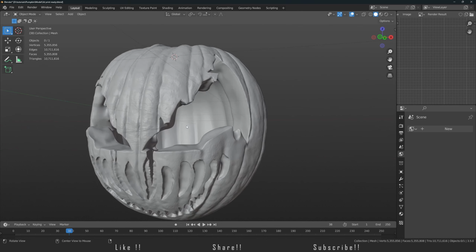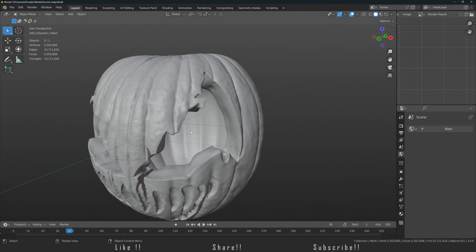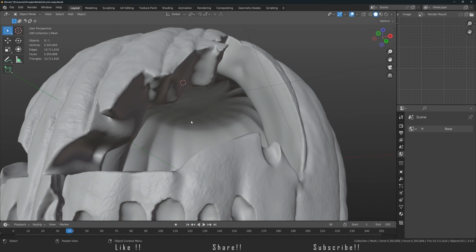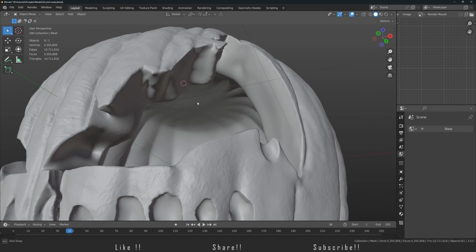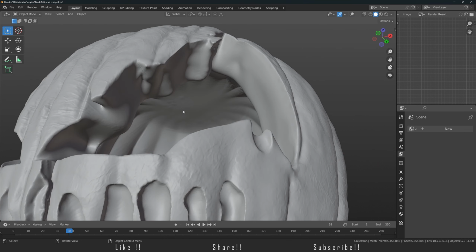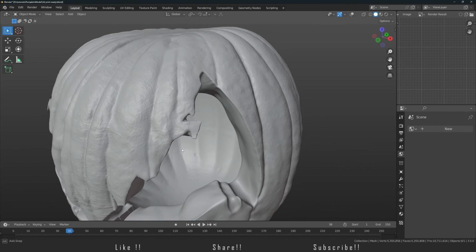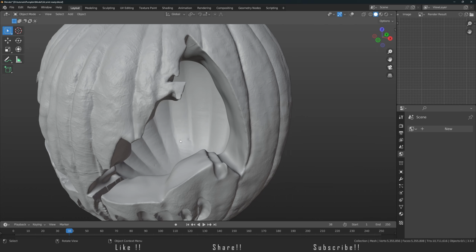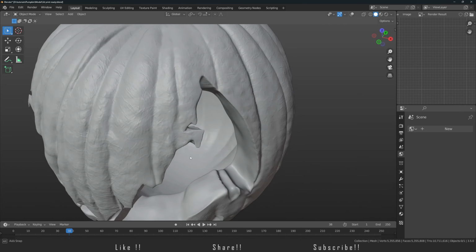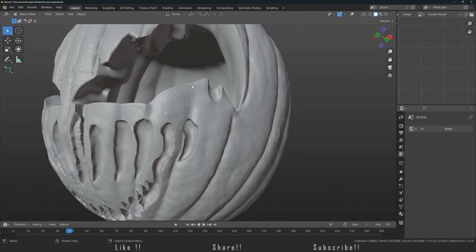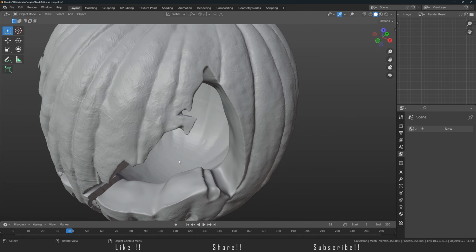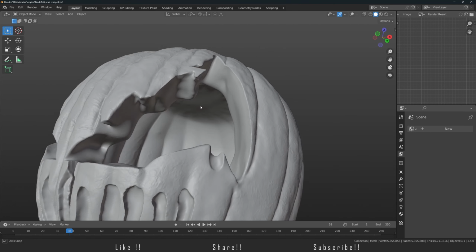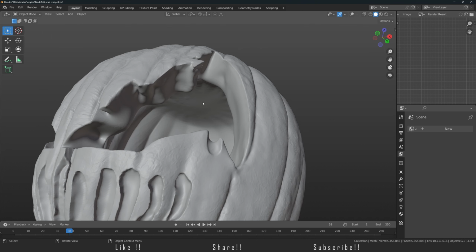The reason that I'm not using this hole is because if you are familiar with 3D printing, you're going to realize that this particular part cannot get 3D printed without the use of support, because if a printer is printing this part, it is just going to fall down, gravity. And because of that, Cura, the software that I use for 3D printing, is going to put supports that go from the bottom, like from this particular area to this, so that it can support this particular part.